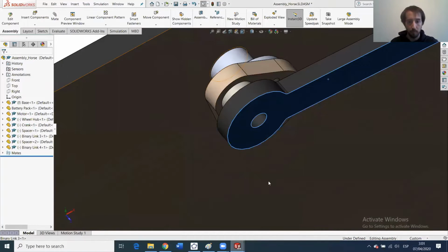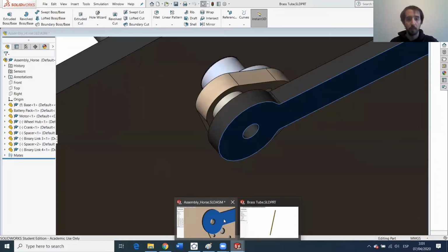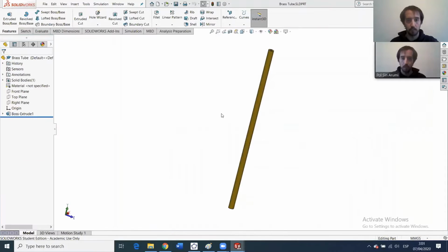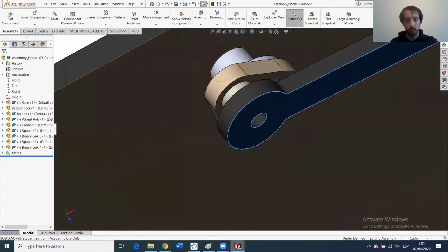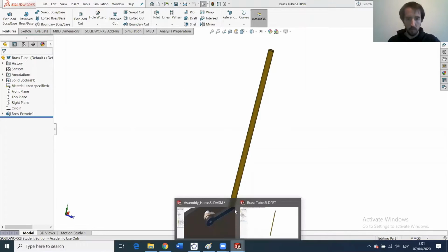And if we make another hole here for the second crank, then the two cranks will be in phase, because the first crank will transmit the movement to this bar, and the bar will transmit the movement to the other crank. I'm sorry if I didn't explain really clearly, but you will see really well how it works when we build it.